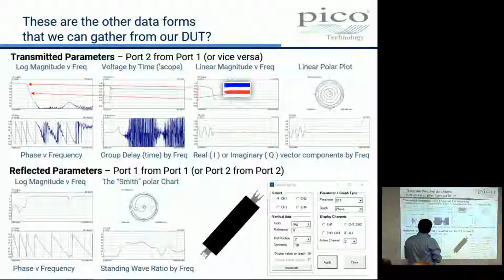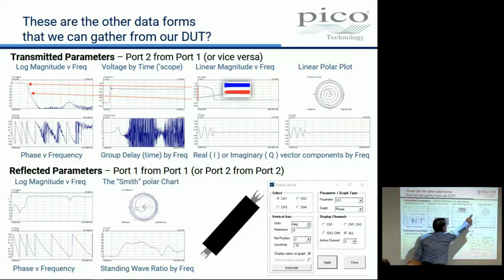Now, it doesn't tell us that much because we can't see anything along here. There's nothing going on out to 6 gigahertz, right? So that plot is of limited usefulness to us in the context of a VNA. Let's instead change this scale to log, in which case that whole bit there, you'll agree on a scope you can see 1 down to 1%, say. And if you map 1 down to 1% across here, it maps to 0 to minus 40 dB.